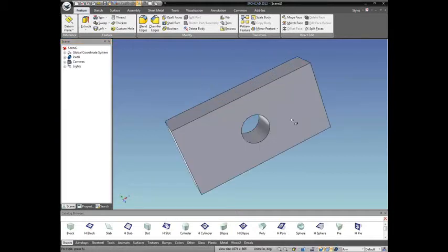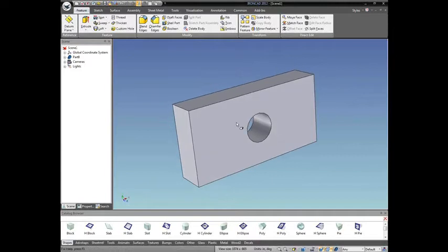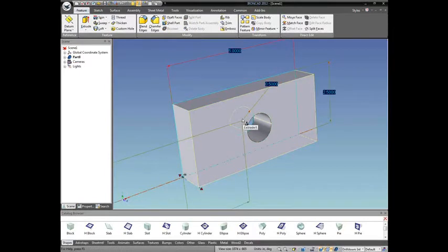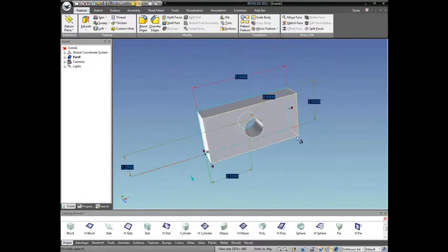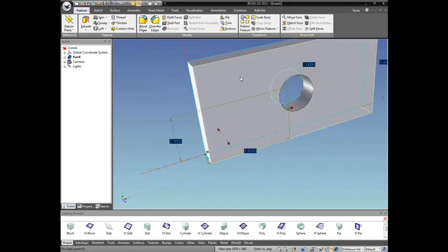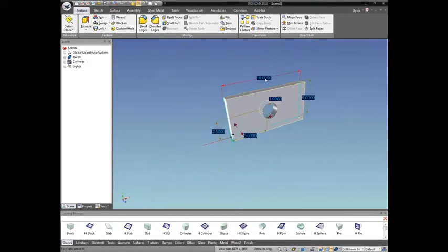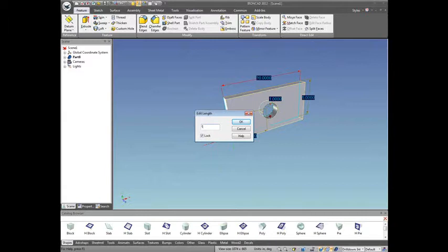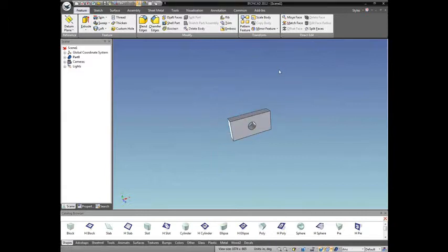All right. So we got that there, and when you select the IntelliShape, you see the dimensions, and you can actually double-click and drive this from right here. And this could be as far as you go with it if you wanted to, but we can go further and create a few more parameters, and then I'll show you how to create a design variation based around that.